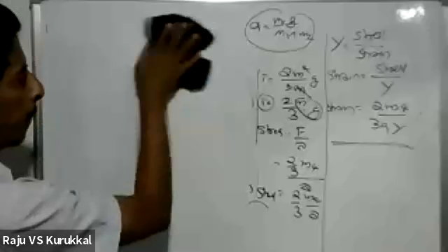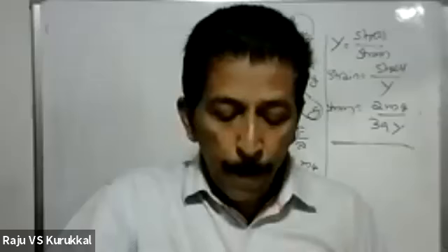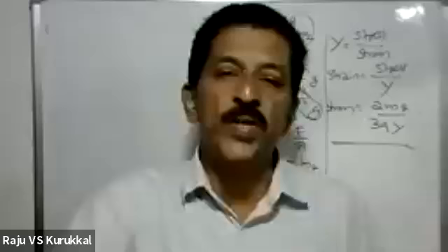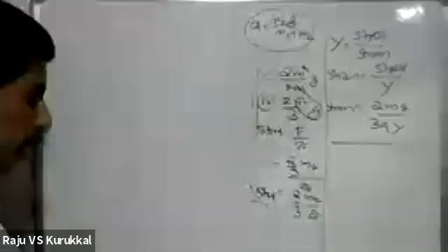The mercury column in the two arms is in level with 10 centimeter of water in one arm and 12.5 centimeter of spirit in the other. The spirit column has a length of 12.5 centimeter and the water column has a length of 10 centimeter. We can draw a U-tube.